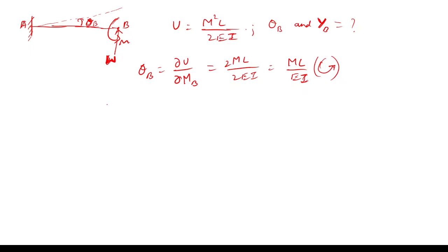After writing the bending moment equation and the strain energy value, I will put the dummy force equal to 0, so that I will get the actual deflection at point B. That is the procedure I will be following. Is it clear or not? Yes, sir. I'm introducing a dummy load because I don't have any W to differentiate with.